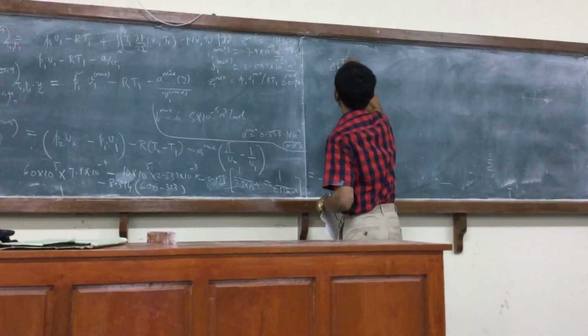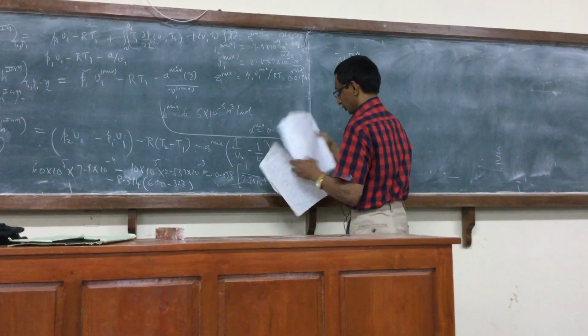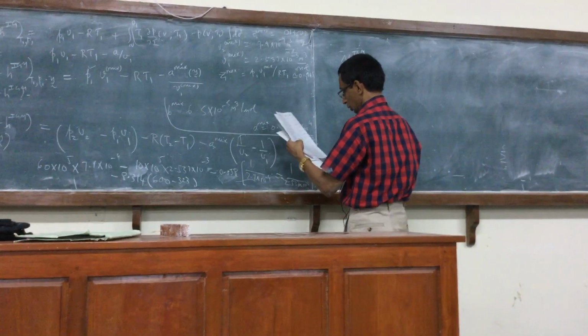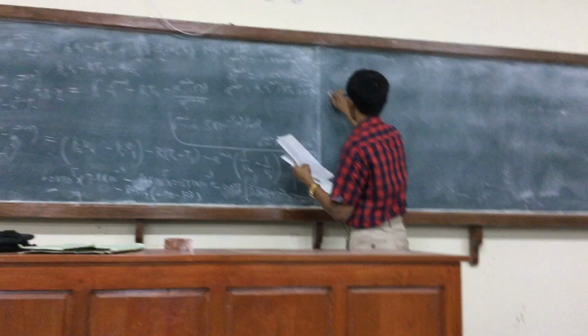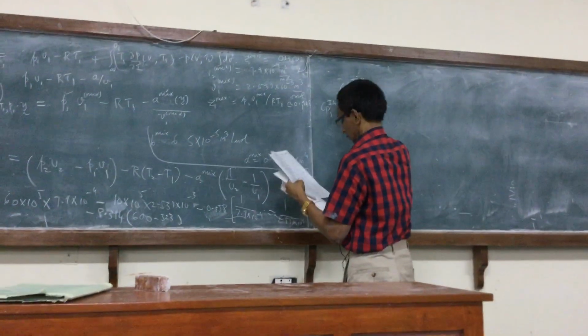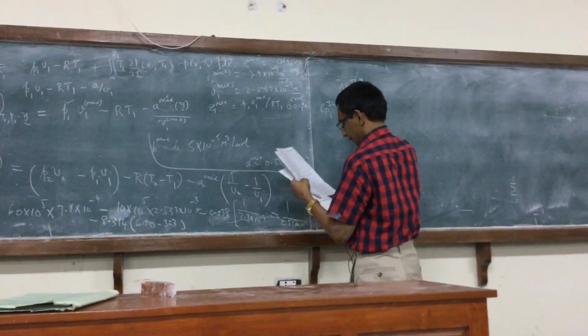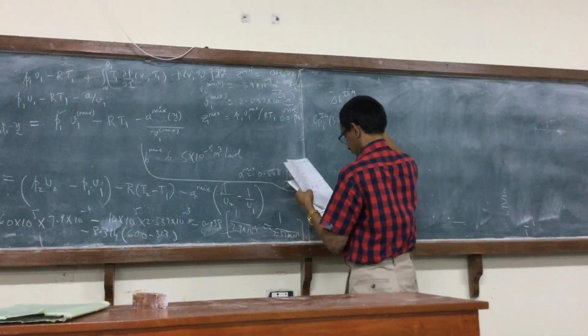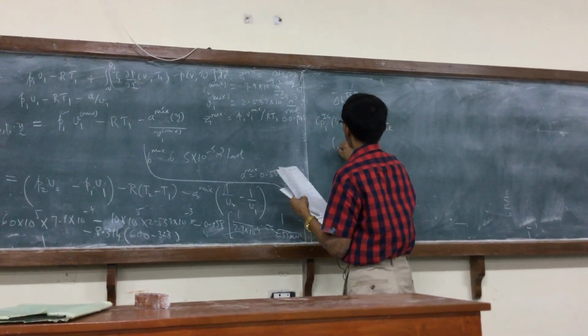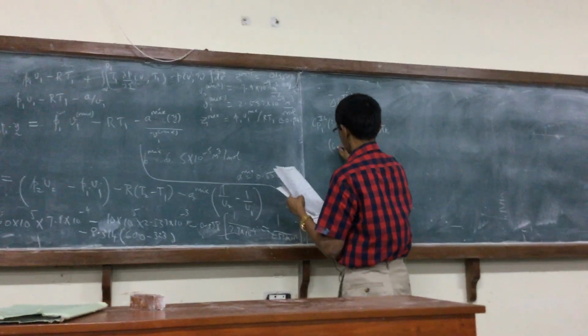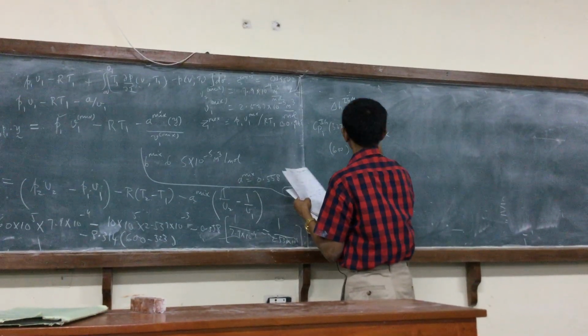So I'm going to assume a constant specific heat for simplicity, but you can do it as varying, since it's not a constant. I'm using some average. The Cp1 IG at 323, I roughly calculated to be 46.37 joule per mole per Kelvin, and at 600 it is 71.64.